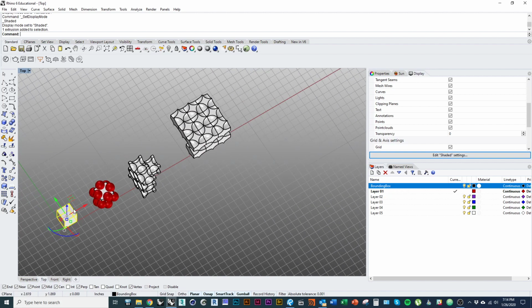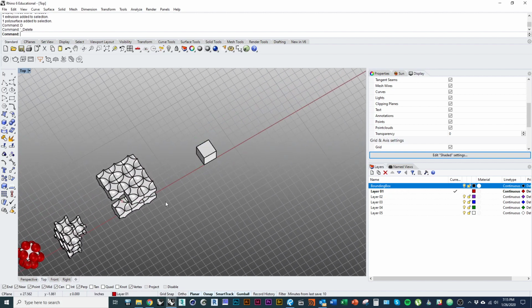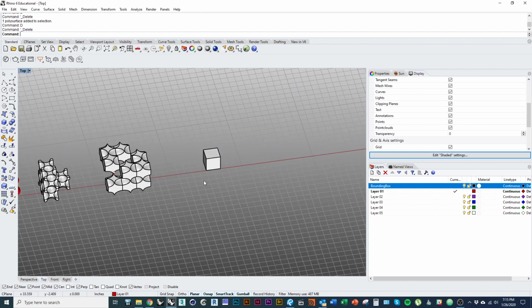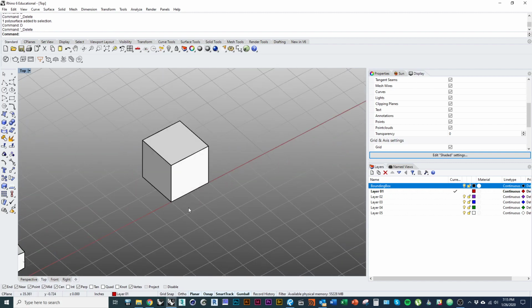And then finally, I'm going to show you the most advanced version, which is what we have on the assignment sheet there. In this one, we're actually just going to carve right through the box rather than making a pattern in the face of the box. And so with this one, I'm going to make a cylinder. I go to my solid shapes here. I'll select the cylinder.